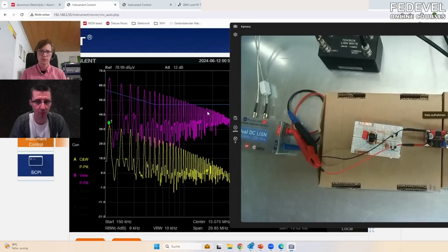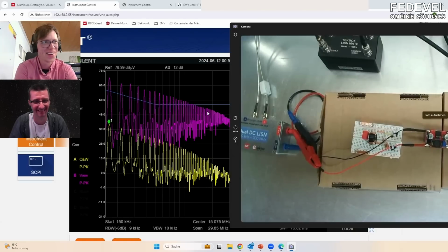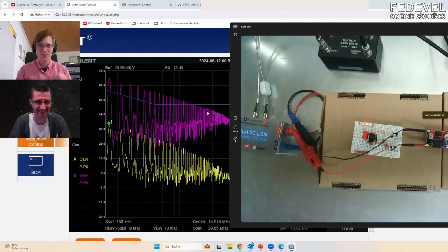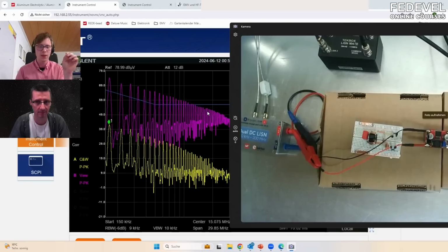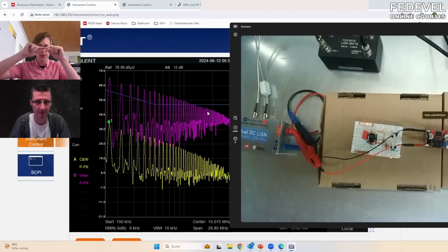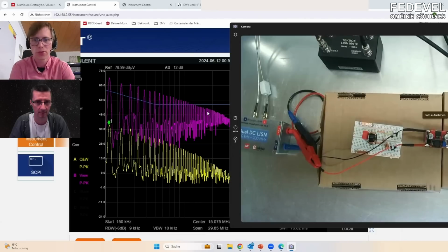So basically, when you have a power supply, it's better if the wires are closer? It's always better when both directions of the current are close together, because the emission itself, the creation of an electromagnetic wave, is a change in the current. So when you have a load and you accelerate it, you will have an electromagnetic wave. And when you have one very close in the other direction, it will create the same wave. Yeah, exactly. They will cancel each other out, and this is the reason why they have to be close to each other.